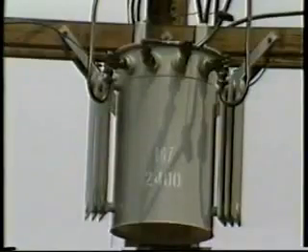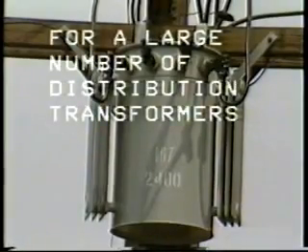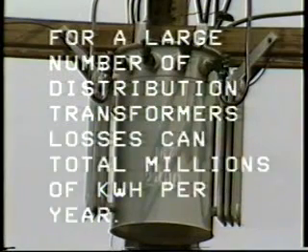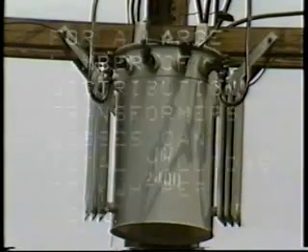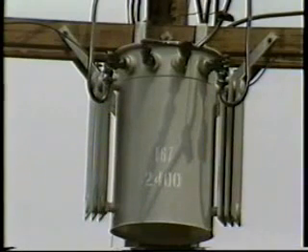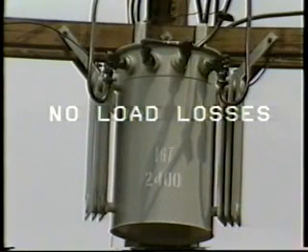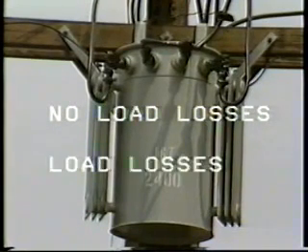Right, let's now move on to our final subject, that of losses on distribution transformers. Given the large numbers of distribution transformers that a utility may have in service, the total energy loss associated with these transformers can add up to millions of kilowatt hours per year. These total losses are made up of two components. One, the no-load losses. Two, load losses.